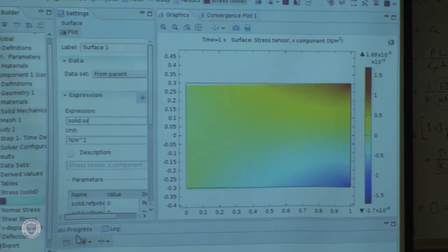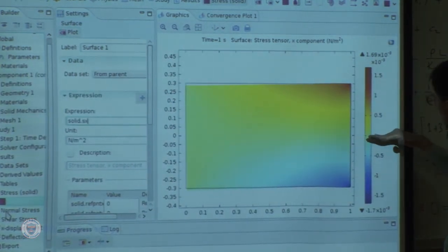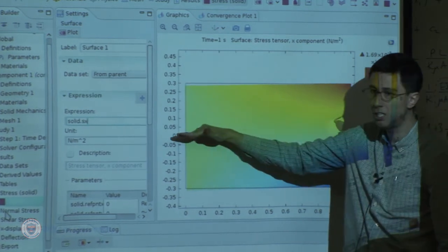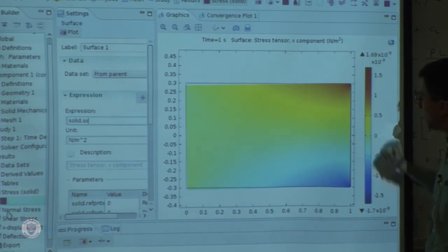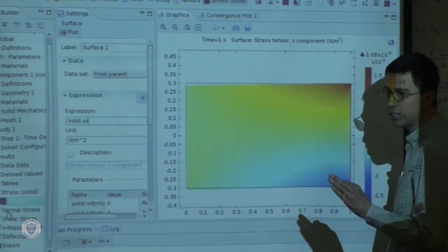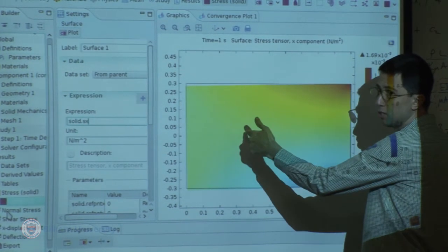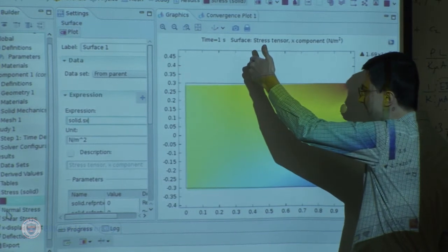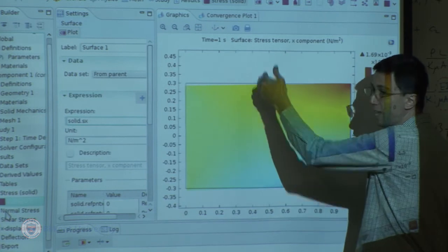And also, we can throw in the solutions from beam theory where they're applicable. So what I'm going to do is several things. One, I will show you the deflection curve. The deflection curve is taken along the neutral axis, x2 equals 0, before deformation. I'm also going to look at the stress distribution as well as the horizontal displacement, U1, distribution, when I take a horizontal cut at a given x value.